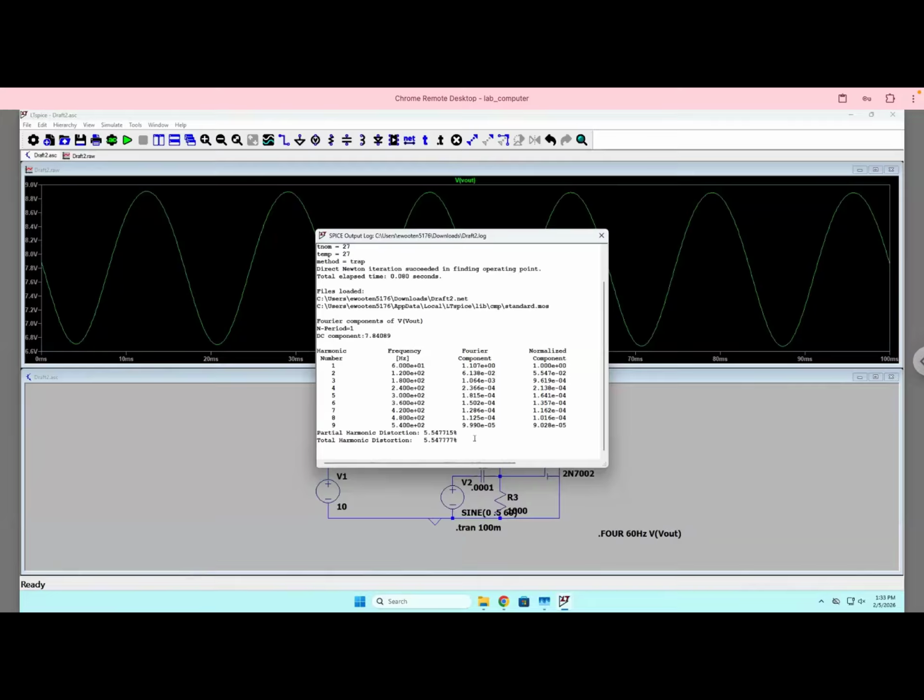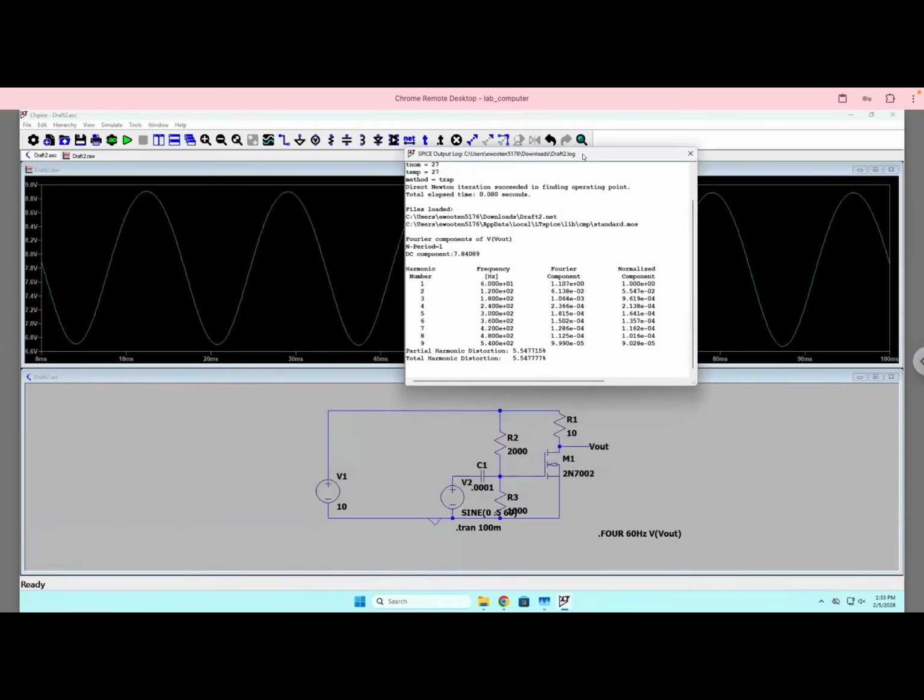They also suggest that you add a bypass capacitor for another resistor that would live here. But I think it's easier just to fiddle with the values of the resistors, R2 and R3, to get that to be lower.